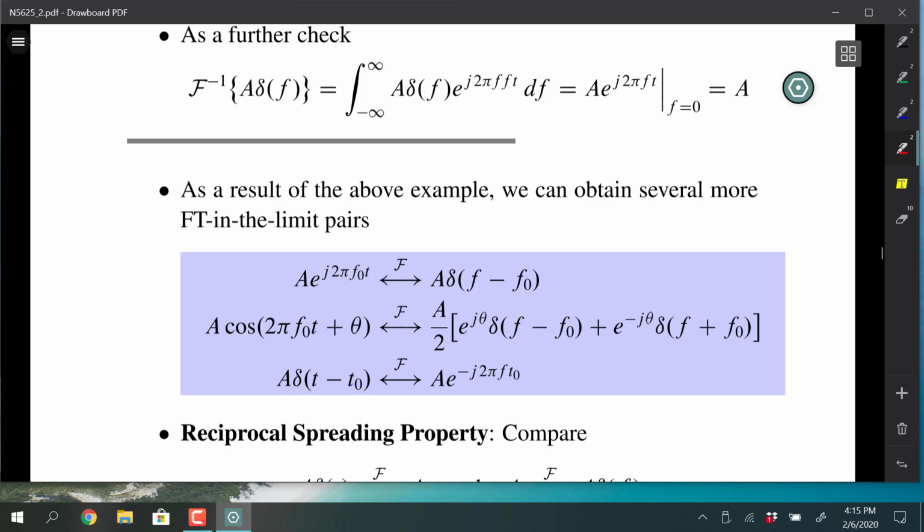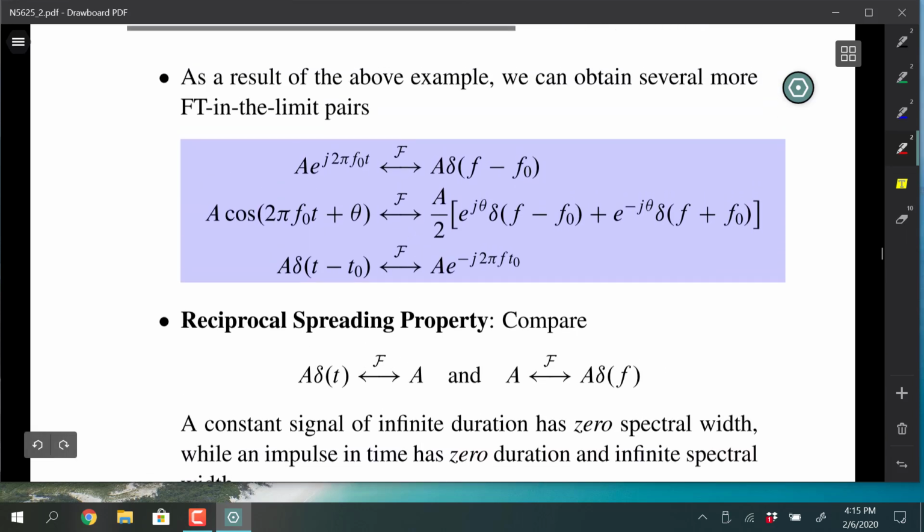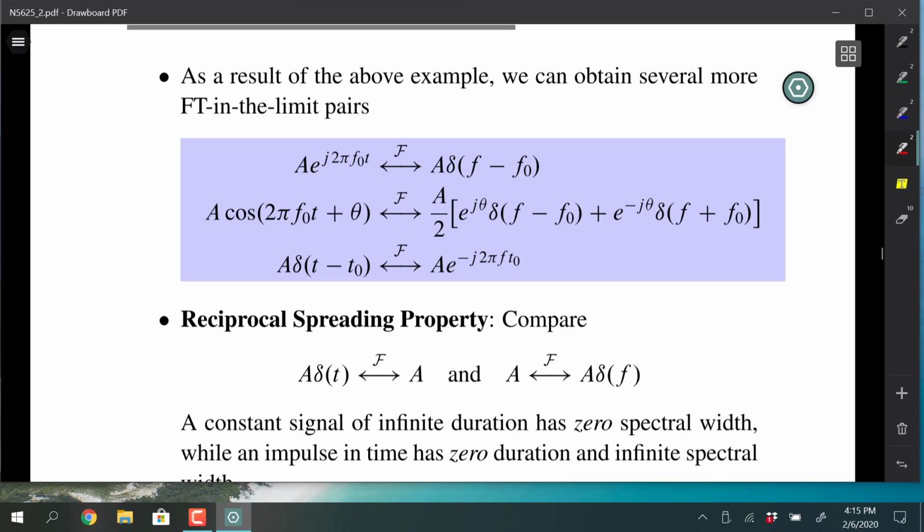We can then put a pair of these together, one spinning clockwise, the other one counterclockwise, and then we can build up the spectrum of a cosine. We can talk about time delaying a delta function and make use of that as well. So we get a lot of cool things that come out of this, and a few more things that I'm going to show you in 5 more minutes, whatever I can get away with for the 5 minutes that remain.